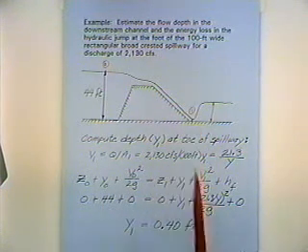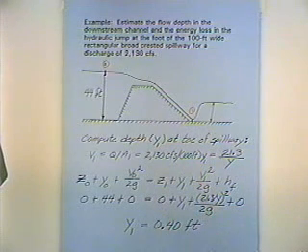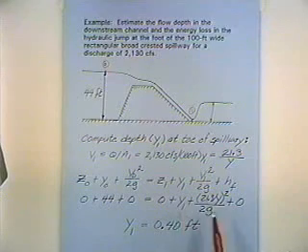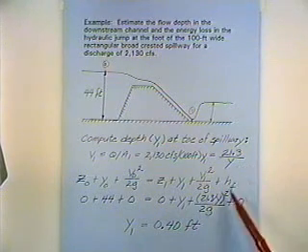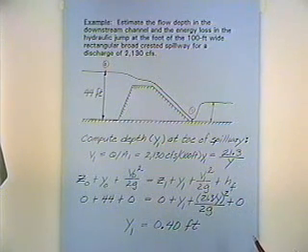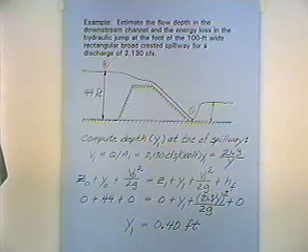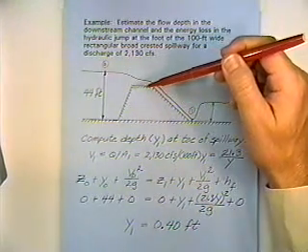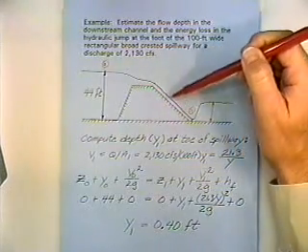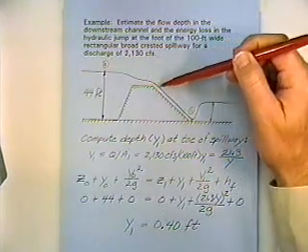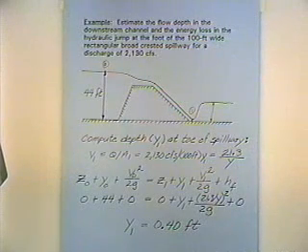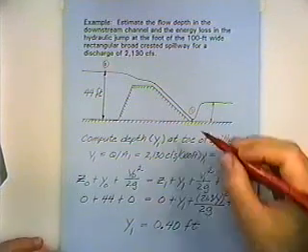Then at point 1 here, again, Z1 is 0. The depth is what we're solving for, Y1. We've got an expression for the velocity we plug in, divided by 2g, and we're going to make an assumption here. We're assuming 0 head loss. We're assuming in this channel that there's pretty smooth flow, very little turbulence, and we'll use 0 head loss and get the depth here of 0.4 feet.